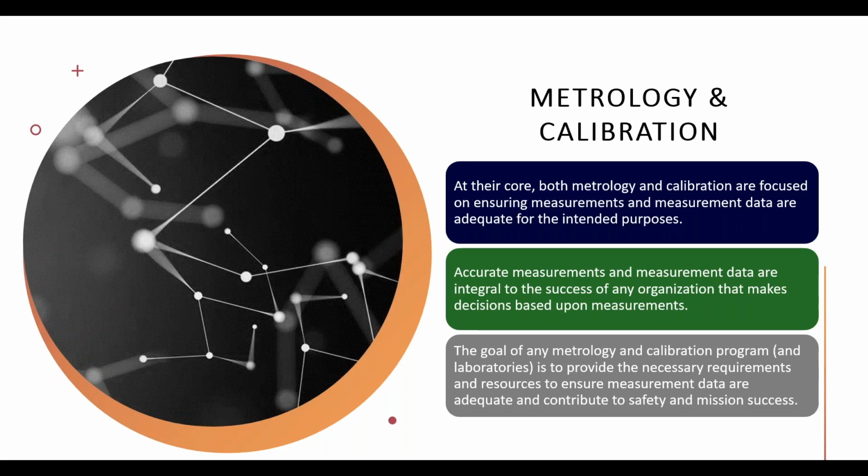If you just send it into the cal lab and say, hey, I just have this meter, I want it calibrated, they're going to give you the same cals they give everybody else. But you might use that device differently from the general user. So you need to let the laboratory know what you're looking for.